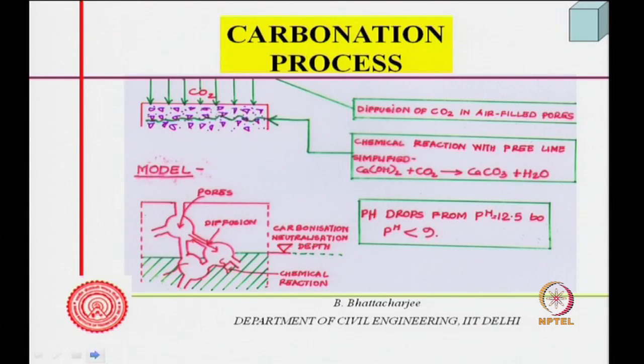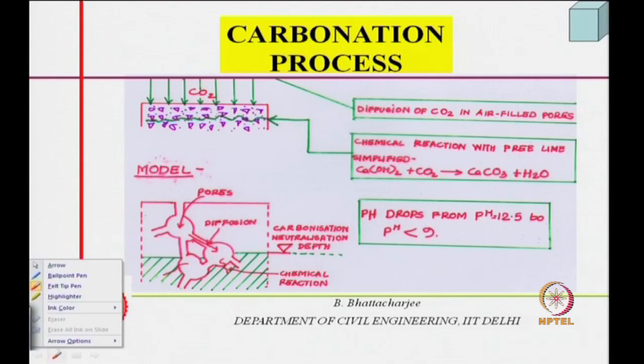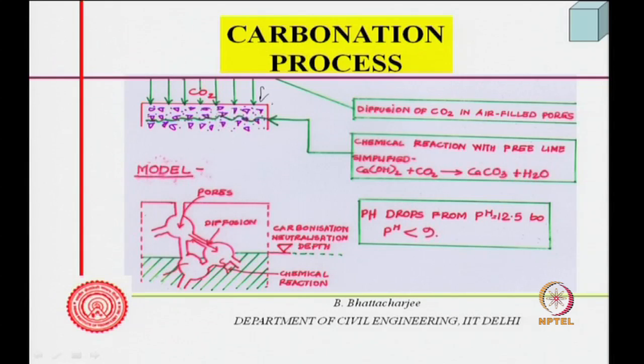Carbonation process, if I look at it, you see carbon dioxide from the atmosphere penetrates into concrete from the surface as shown here, and in presence of moisture, carbon dioxide plus water can form carbonic acid, and this carbonic acid can react with, let us say, sodium hydroxide to form sodium carbonate plus water.